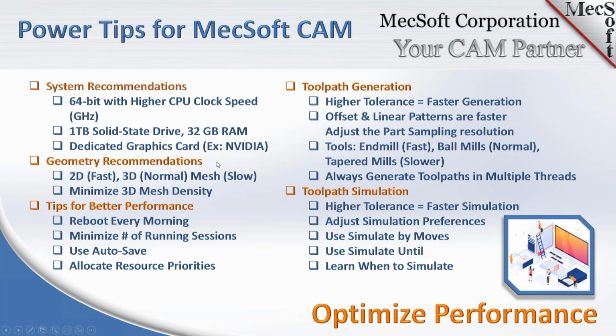And then obviously CAD is highly graphics intensive, so if you can afford it, go with a graphics card versus an integrated graphics on your motherboard, which typically come with any baseline computer, integrated Intel graphics. If you can afford it, get a separate dedicated graphics card such as NVIDIA. That's what we use here, and get as much RAM on that card as you can afford. So the basics here: speed, performance on your drive, max out your RAM, get a dedicated graphics, and get as much RAM on that card as well. So let's talk about geometry recommendations.